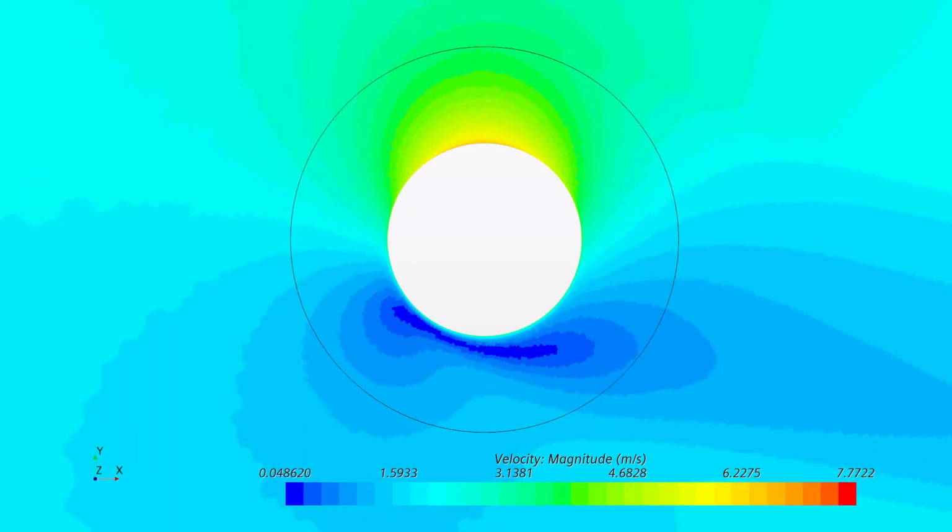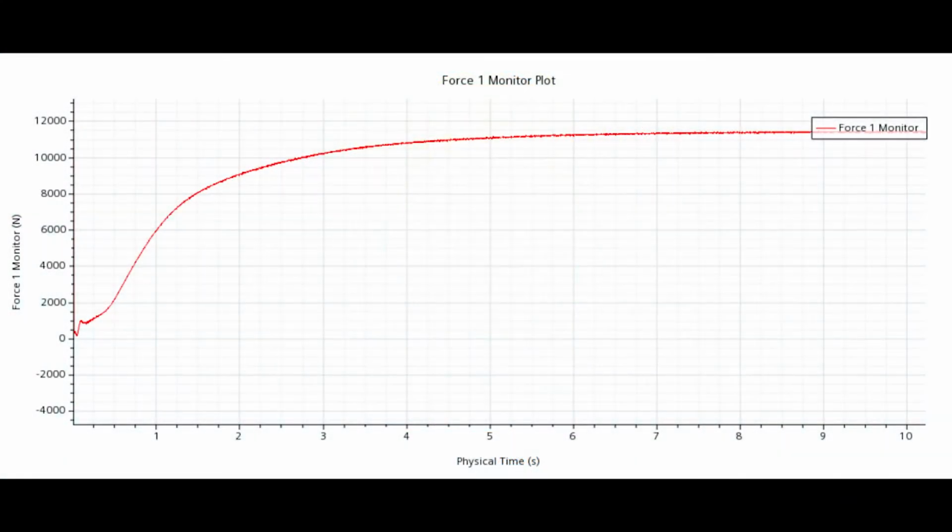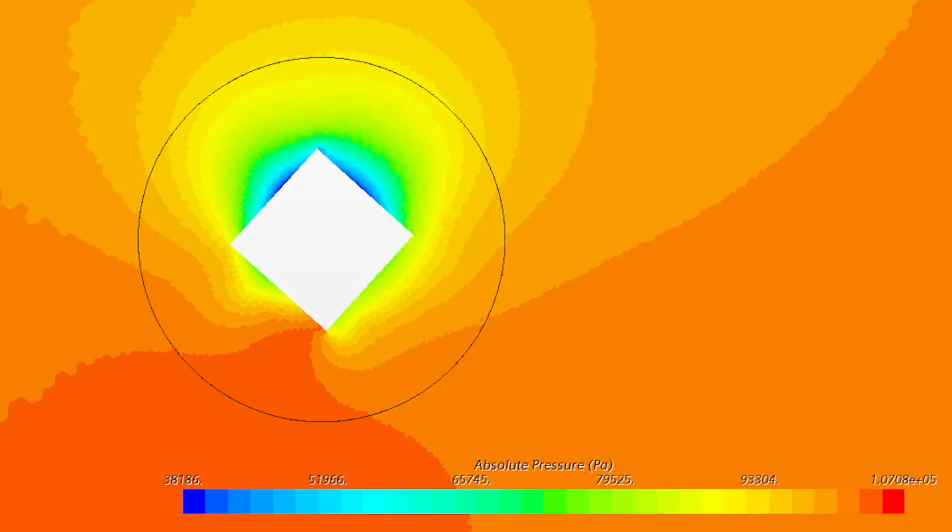However, the precise lift values produced from the simulations differ from the experimental values obtained in a wind tunnel with identical geometries. This could be due in part to the difference in tip-speed ratios, as the CFD model was simulated with a tip-speed ratio of 3.9, compared to the Pezzati study, which analyzed the same geometries for tip-speed ratios from 0.2 to 0.9. The STAR-CCM+ models confirmed higher lift forces for bodies with rougher surface geometries, but failed to predict lift coefficient values that were consistent with the available scientific literature.